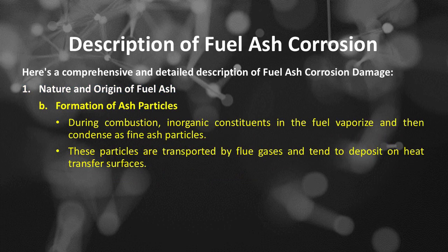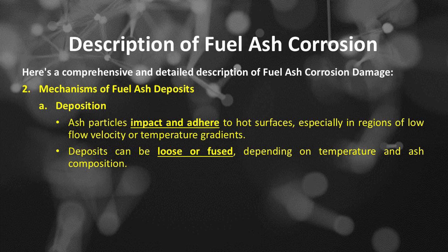Number B. Formation of ash particles. During combustion, inorganic constituents in the fuel vaporize and then condense as fine ash particles. These particles are transported by flue gases and tend to deposit on heat transfer surfaces. Number 2. Mechanisms of fuel ash deposits. Number A. Deposition. Ash particles impact and adhere to hot surfaces, especially in regions of low flow velocity or temperature gradients. Deposits can be loose or fused, depending on temperature and ash composition.